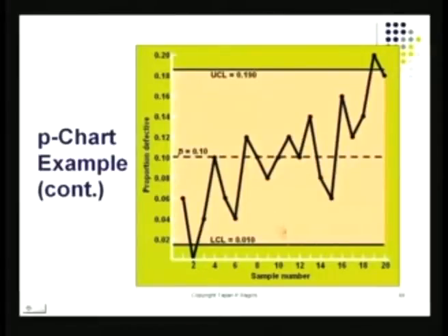Well, when this was done, you had a suspicion that perhaps 18 defects were too many, right, when you looked at the 20th sample. And see what they found? They plotted the P chart with the upper and lower control limits as calculated. After plotting the chart, they did find that in this zone the chart went beyond the control limit. So this is an opportunity for finding the issues and problems there.